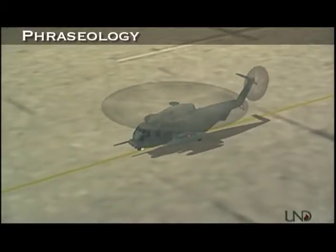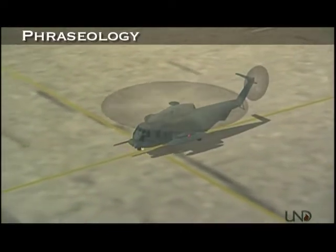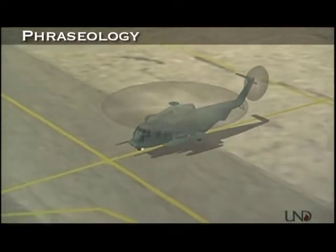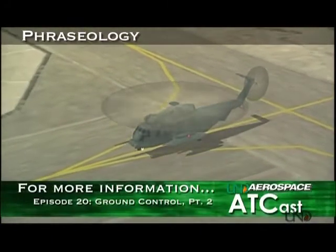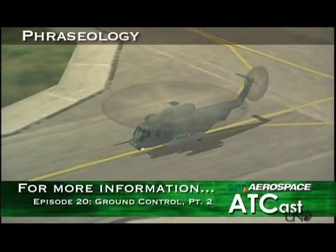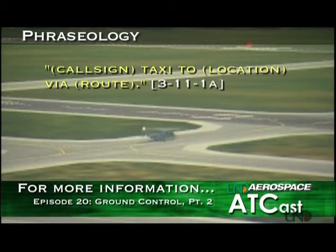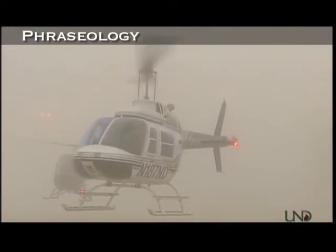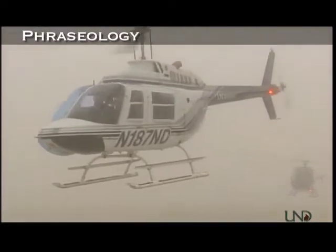Some helicopters have wheels, and will sometimes want to taxi on their wheels because it's more fuel efficient than either hover or air taxiing. This is called ground taxiing, and the phraseology is identical to what you'd use for fixed-wing aircraft. See episode 20 for more in-depth coverage of that phraseology, but as a quick review, the format is aircraft call sign, taxi to the location via the route. For other helicopters, replace the word taxi with either hover taxi or air taxi as appropriate. Wheeled helicopters can also taxi this way.